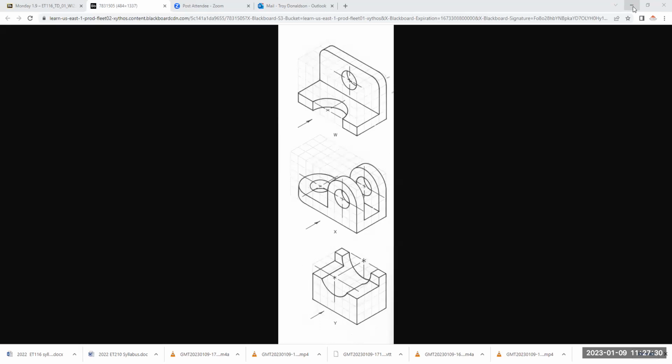Like if I wanted hidden, I would just choose that one. If you had a big drawing, you might use hidden x2. If you had a little drawing, you might use hidden 0.5. That's why you've got 2 of them. More than likely, you're still going to have to adjust that line type scale because it's just not very intuitive. But I'll say, okay, all that did was load it. Now it's here, hidden.